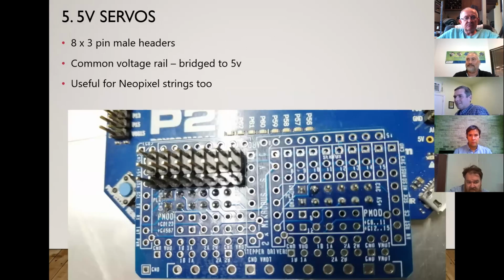The other thing I was just referring to before was 5-volt servos. If you want to just link that bus bar across to the 5-volt end, then you can connect up 8 servos onto that block of headers.